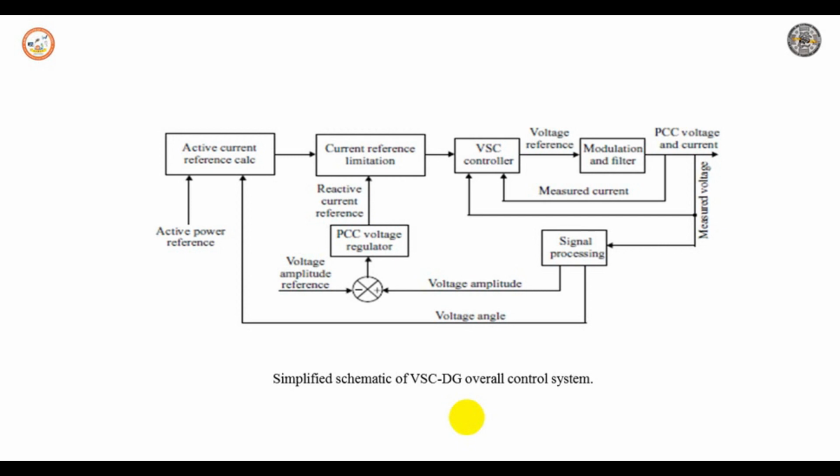So this vector will provide less reactive current that is required for voltage regulation, hence the voltage is not exploited fully. Other current limitation algorithms are also possible if the reduction in active current of DG lies within an acceptable limit.